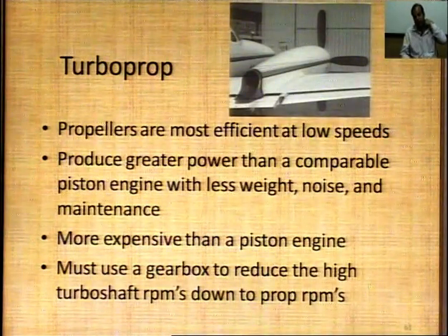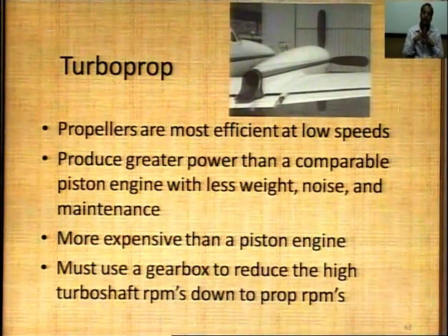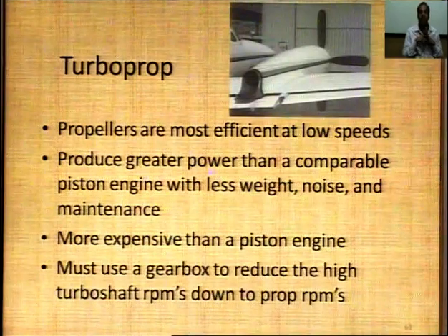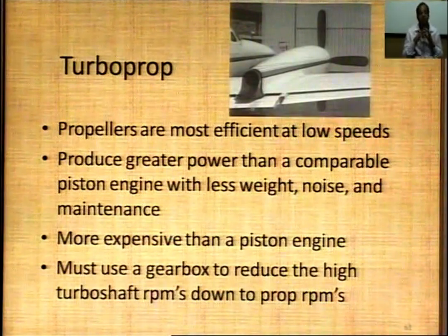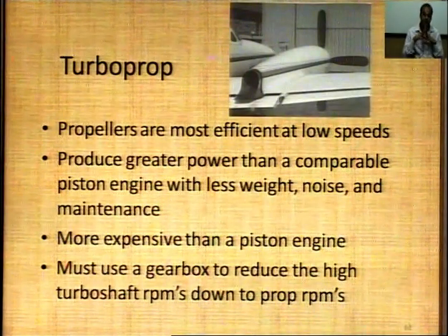Now let me discuss the turbopropeller. Turbopropellers are more efficient at lower speeds, and second, they produce greater power than a comparable piston engine with less weight, less noise and less maintenance. The basic disadvantage of the turbopropeller engine over the piston engine is that it is more expensive.